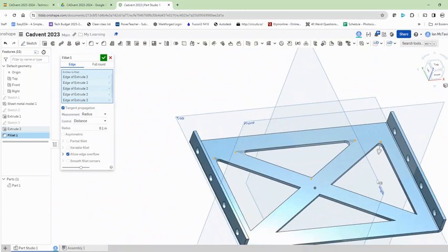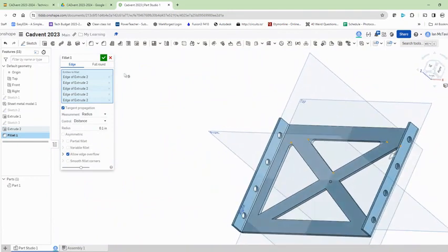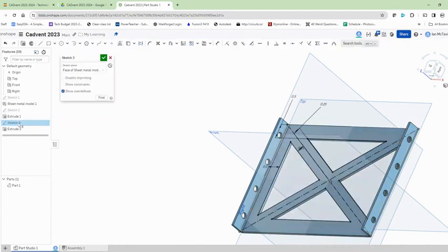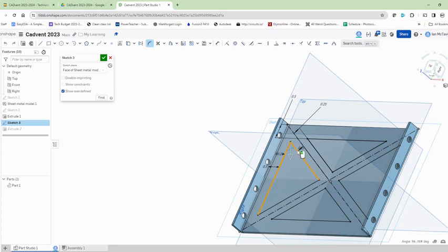And I think there's faster ways to do this. Yeah, this is taking too long. So if I go back into the sketch, if I do the fillet, it's a little bit easier because I'm just clicking the two lines, 0.1. And once I've done one measurement, I don't have to, it keeps using that same measurement. So it's a little easier for me to create it. It's finding that balance. At what point is it easier to do as a feature?